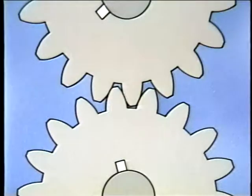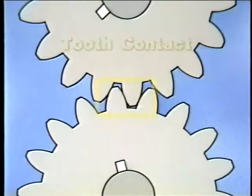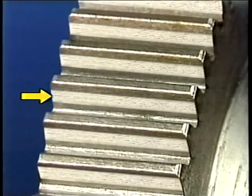Well, now that we've discussed backlash and end play, let's focus on another term that's commonly used when discussing the operation of gears: tooth contact. Basically, tooth contact describes the area where gear teeth touch each other while they're meshing. Tooth contact may appear as a band on a gear tooth.